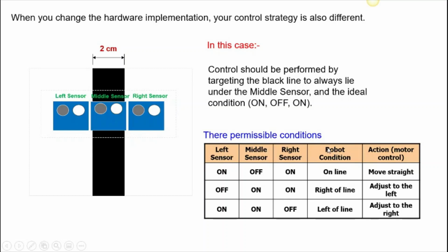Okay, so you must specify the robot condition on that particular sensor status, and then according to that condition, you need to do some action to adjust, the necessary action to be taken when the robot has been swayed to right or left, or maybe the robot has been going out nowhere in your testing platform. So with the truth table, you know whether you have covered all the conditions that could possibly affect the navigation of the robot.